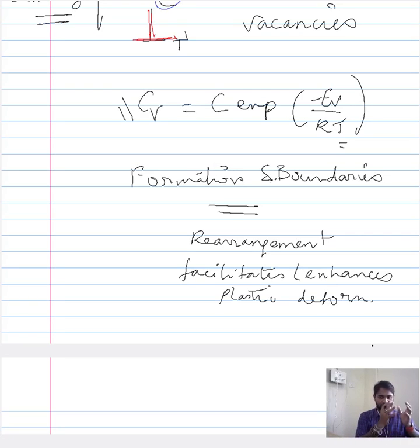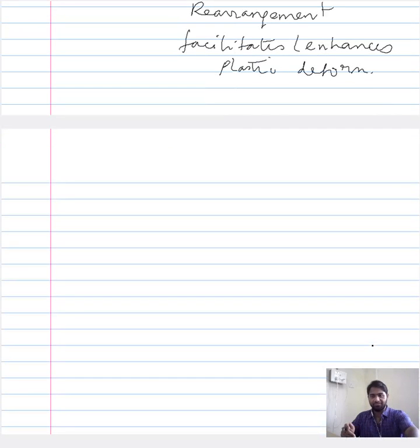When you just talk about the stress component, when you increase the dislocation densities, the plastic deformation is impeded. Now, because we are considering increased temperature, we have decreased that dislocation density by the annihilation and the rearrangement. So if you want to compile these two, because of the stress component, the dislocation density increases. Because you keep on imposing the stress, new dislocations begin to form and they interact and impede each other. So this ultimately restricts the plastic deformation.